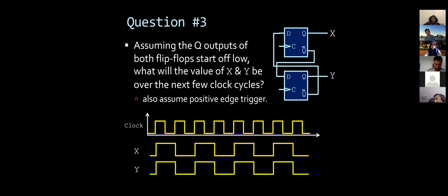It's the same. Remember when I explained the flip-flop, the best way to think about it is you had a water pipe, right? And you have two gates, and you can open one and close the other. So when you open the first one, some water goes down, but it doesn't go all the way through the pipe. It just goes to half of the channel, and then it's blocked by the second gate. Then at the same time, you move both gates, 1 to 1, 1 to 0, and one gate opens. Whatever piece of water you had goes through, and the rest is blocked. To get another piece of water next time, you need to go through the full cycle. And then you can imagine someone magically, every 1 nanosecond, doing this trick, moving those gates up and down.